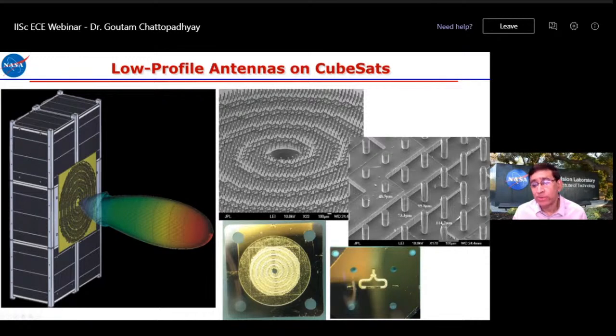What we did is we developed these pins of different heights. You can see here. At 300 gigahertz, the longest of these pins is about 120 micron. The thickness of our hair is about 50 micron to 150 micron. So we are talking about the thickness of this antenna being one thick hair. As a result, it is very, very low profile.